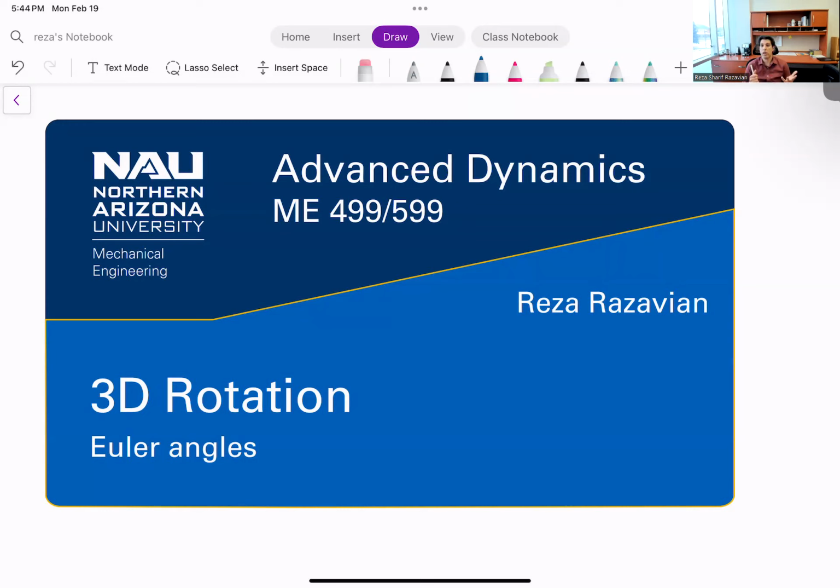But a rotation in 3D is essentially a 3 degree of freedom motion. So ideally, you only need 3 numbers to describe any rotation. Any of the remaining 6 numbers in the rotation matrix are kind of unnecessary.